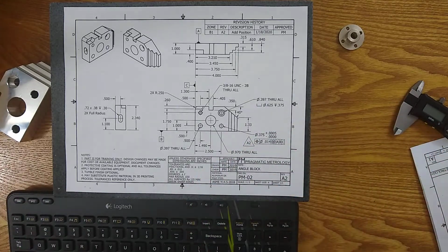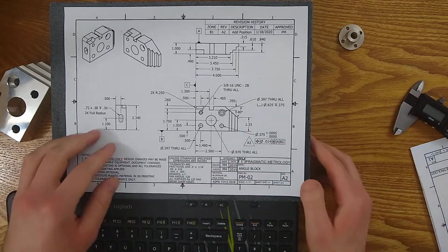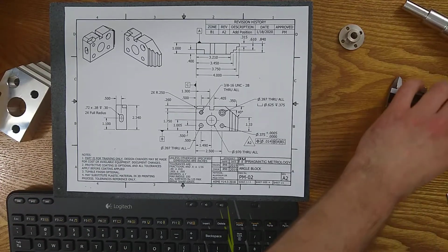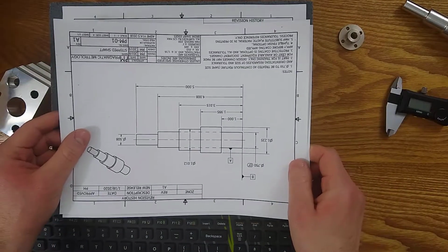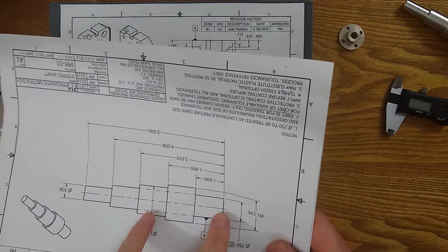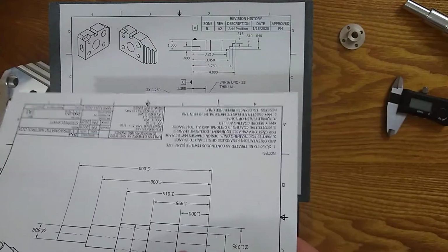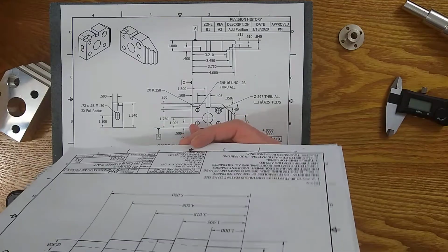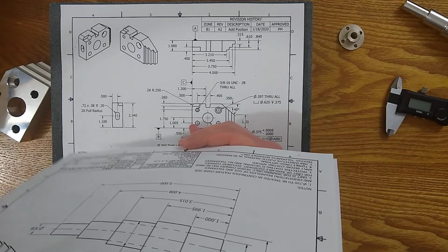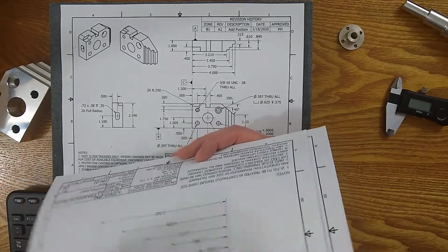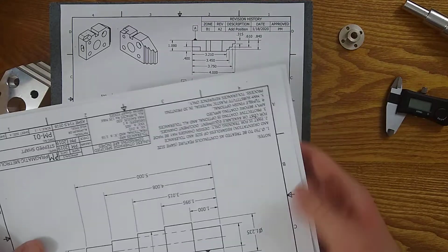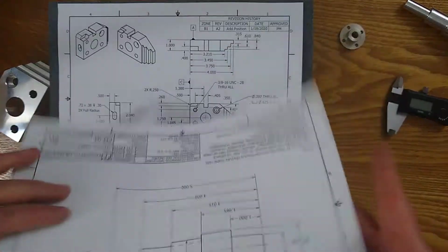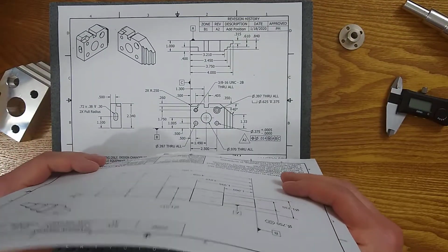The more prints you look at, the more you'll realize there's some symmetry. When you look at the step shaft drawing, I've defined this the way the industry defines it. There's nothing special about what I did. But you'll notice the diameters are implied to be on center line, and I don't actually have anything that tells you that. There's an implied relationship there that won't be called out, and you still have your title block to go with. You just rely on conventional wisdom, and if you're not sure, ask.